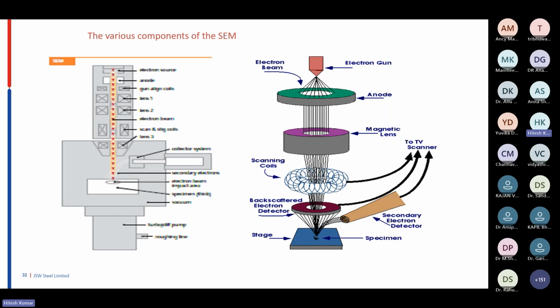So what we used to do is make a different kind of holder in which the sample is tightened with the help of a screw. It is tightened in a proper way, and we used the SEM in low vacuum mode, so that the magnetic effects are quite less. We did this with the magnetic steel samples, but I have never used powders, so I can't comment on that.